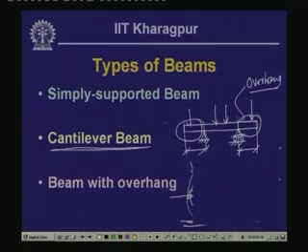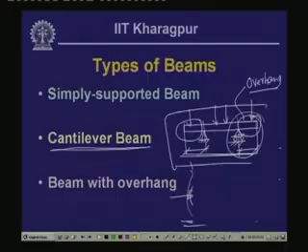Now, this part is something like a cantilever beam, but in this cantilever beam here the rotation is allowed, because it is supported with a roller support at this point, which has a vertical constraint. Because of this overhang it is expected that it can generate moment and also rotation, but being a roller support, that cannot resist any rotational aspect over there. So, there is expected to be rotation. This kind of beam member we generally call a beam with overhang.